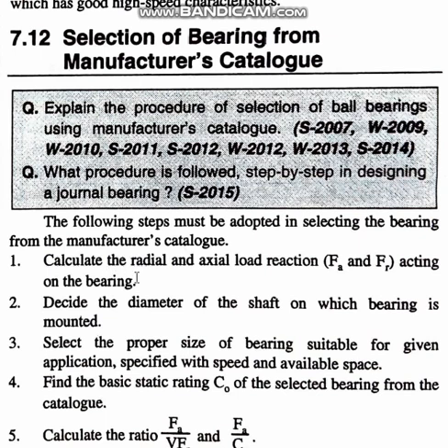The first thing is you have to see what is the radial load. Radial load means the load that is coming perpendicular to the axis of the shaft. Axial load means the load coming from the side, like side thrust. Radial load is FR, axial load is FA. These two you have to find out.